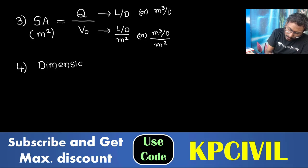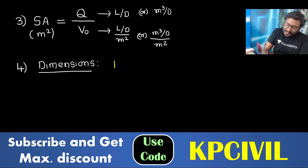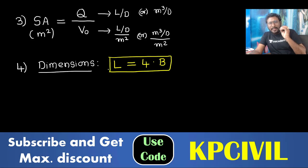According to IS codal provisions, the length of a primary sedimentation tank is maximum 4 times the width. L is equal to 4B. So you may take L is equal to 2B, 3B, or 4B, but not more than 4 times.